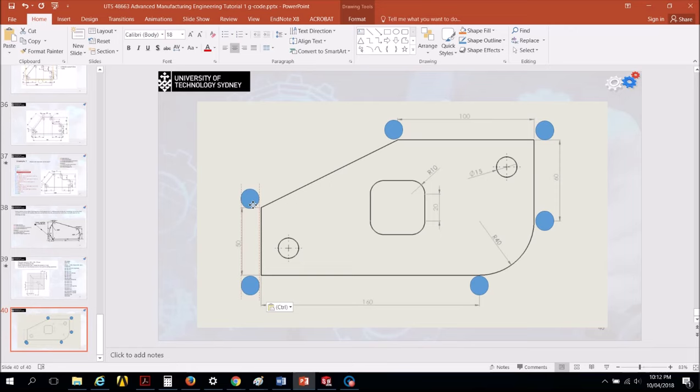Okay, and then we have to go down. Now this is for the profiling, but the trick is how we are going to hold the part. This is a very important issue. So it's much better to divide the work, the programming, into phases or setups. So if I'm going to have a block, just a rectangular block, and I would like to do the cutting on it, I have to hold it before I get to do the work.